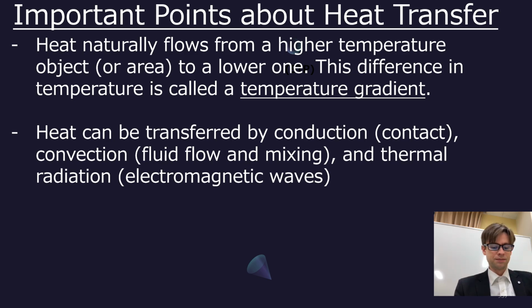Then thermal radiation. This is important as well. It's electromagnetic waves. So you might not realize it, but when you have an oven or a fire, most of the heat coming off that is not conduction or convection, but rather infrared waves, I think caused by the particles in the fire or heat source accelerating or decelerating, changing their speeds. As they do so, they release electromagnetic radiation always, and that's IR usually for low temperature things. Low in a broad sense, I just mean not superheated.